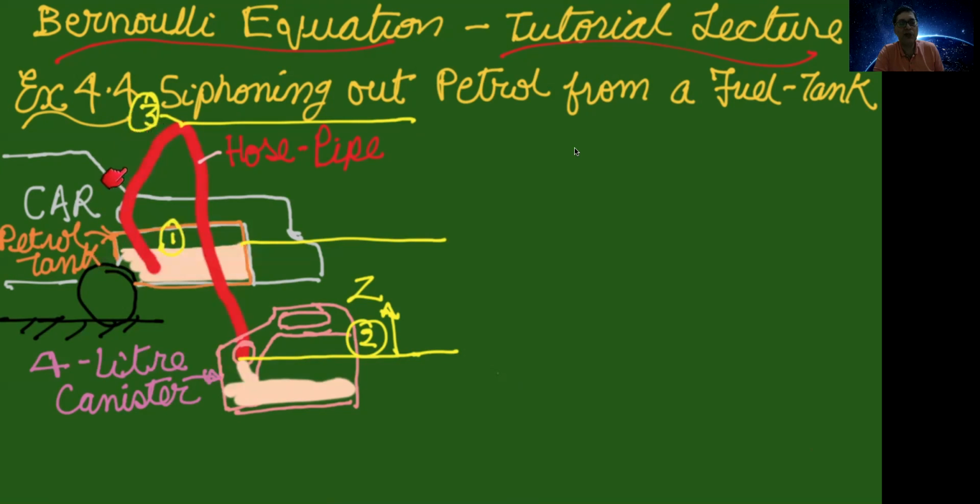And along with the change in the potential energy, kinetic energy is constant, and you know that Bernoulli's equation is basically the law of conservation of mechanical energy, where the mechanical energy consists of three energies: flow energy, kinetic energy, and potential energy. So for flow in a pipe, kinetic energy is constant. So it's basically a balance between the potential energy and the flow energy.